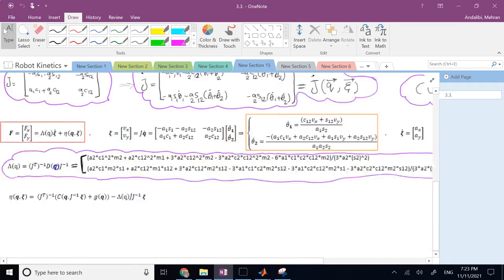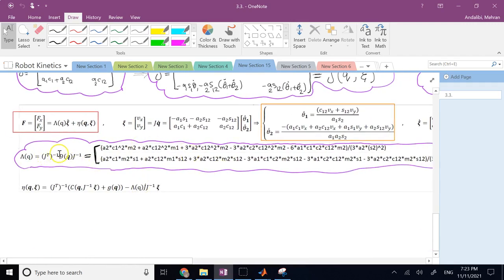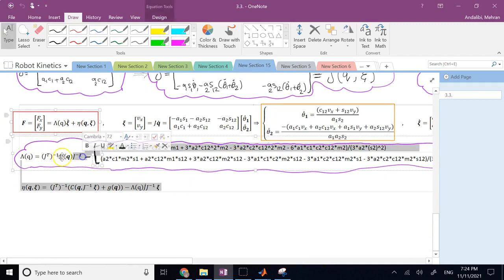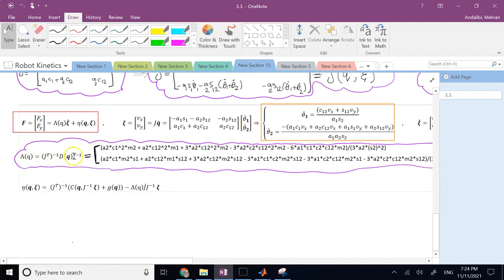And you might say, why? Well, the main reason is this J inverse. That's the major thing. The transpose of J is not a big deal, but the inverse is. Because you're inverting J, and that brings more and more stuff to it, and you also have J dot, right? So you are bringing more and more terms and multiplying them together. So if you look here, I have a 2 by 2, another 2 by 2, another 2 by 2, and then a 2 by 1. There are tons and tons of terms here multiplied together. And the same thing here too, multiplying 3 matrices.